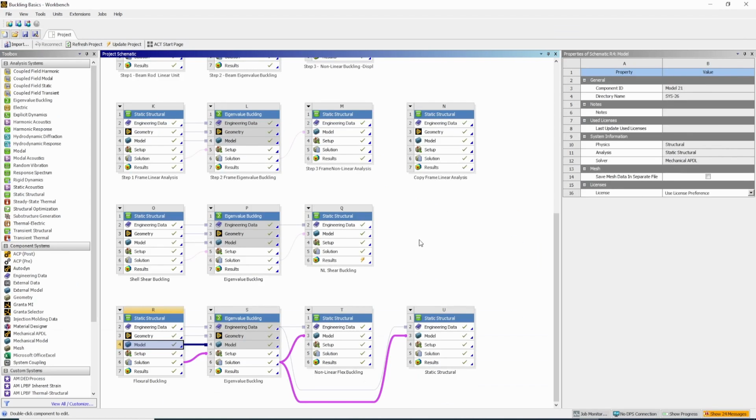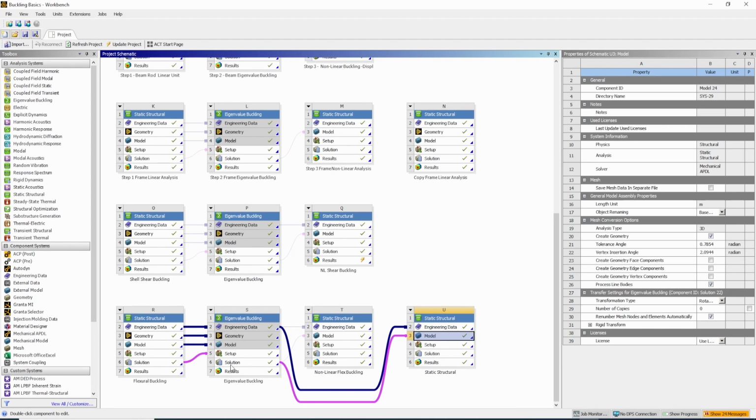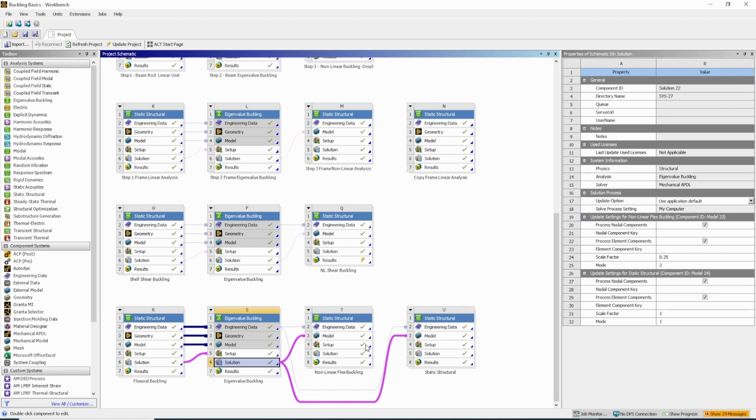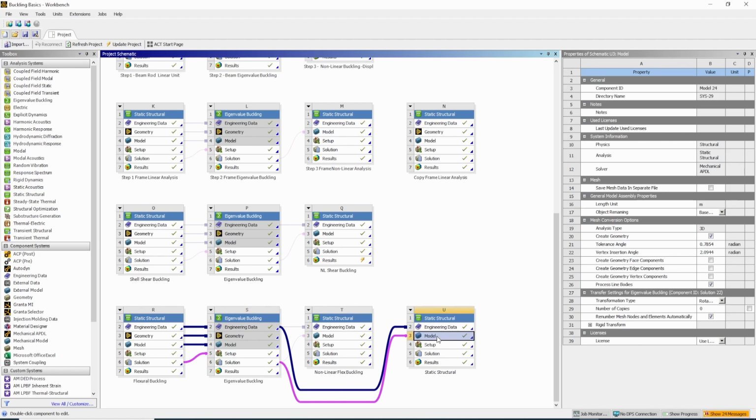Let me just move on to step 3 here. So for the nonlinear analysis, I'm importing the mode 1 buckled shape at a scale factor of 1. It's not clear which mode we should bring in because the modes are very close to each other, but I'm starting with 1, and let's see how this thing progresses. So I'm just going to open this model here.